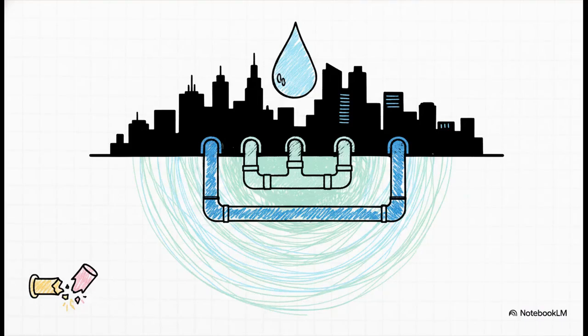Now, as a water treatment operator, your primary goal is to ensure the water leaving our facility is perfectly safe and stable. We use potassium hydroxide, which you'll often hear called caustic potash, to adjust the pH of the raw water. Why? If the water is too acidic, it actively corrodes the community's underground piping infrastructure. By carefully injecting this KOH, we raise the pH and protect the entire city's water grid. You really aren't just handling a chemical here, you are literally preserving our public infrastructure.